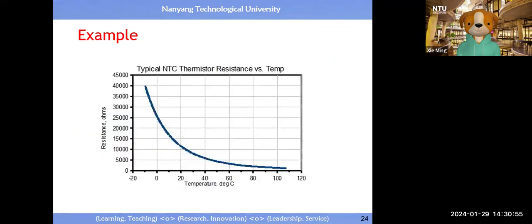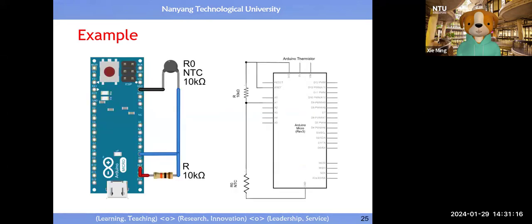right? So, for example, this is not linear, because the relationship between temperature and resistance is not linear, right? So it's quite easy to find the curve to fit this one. Once you know the curve fitting, then immediately you know how to rectify the reading. So it's not a big issue. It's quite simple.